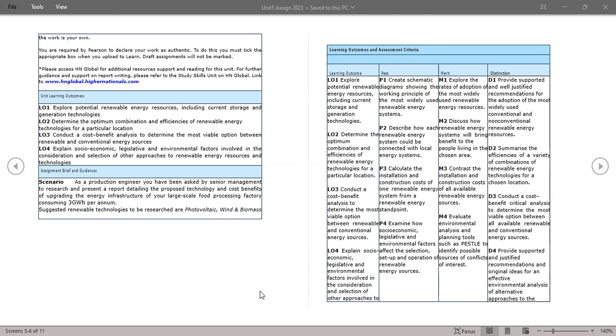If you typically take the meter in a house, 1 kilowatt hour means that, for example, if you had a 1 kilowatt electric oven on for 1 hour, you would use 1 unit of electricity. 1 kilowatt hour is the unit of electrical energy. So load factor is related to energy, not necessarily power, because it's over a period of time. So it's how many hours in a year, per annum: can you get the rated power out against the number of hours in a year?